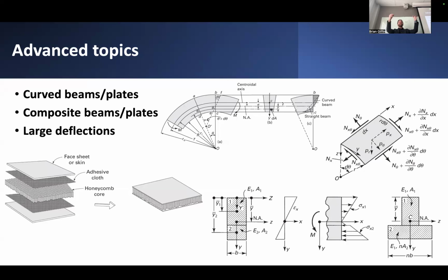And if you think about what would happen if you were to pinch the ends of this curved beam and just pull it axially, basically stretch it, if this thing were initially straight, it would just yield perfect axial deformation and axial stress through this linear segment.